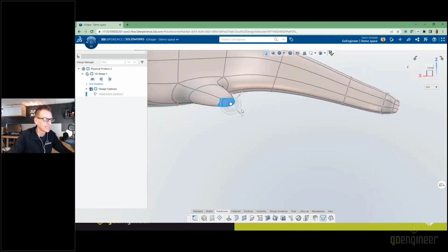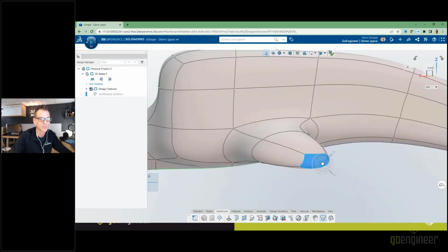Now, sometimes it's sitting on the screen in this particular XYZ orientation. But like I said before, when you click the robot, you have control over it. Right-clicking on it now allows me to have it orient itself based on the selected geometry, which is going to be variable based on the normal to whatever I've picked, or a specific orientation on the screen like XYZ.